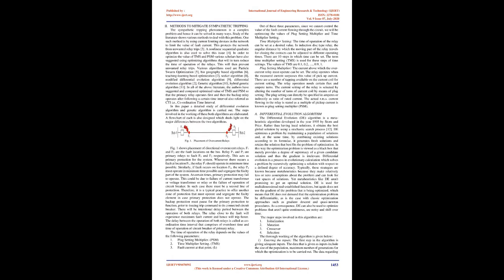Protective relays should identify the fault with the help of voltage and current transformers, and selectively eliminate only the faulty section from the remaining system by tripping a suitable number of circuit breakers. Overcurrent relays respond to the magnitude of the input current and work when this magnitude surpasses the predetermined pickup level. When this level is surpassed, the relay closes its trip contacts and circuit breaker trip coils are energized. The relay has to perform this with extreme sensitivity, selectivity, and swiftness.